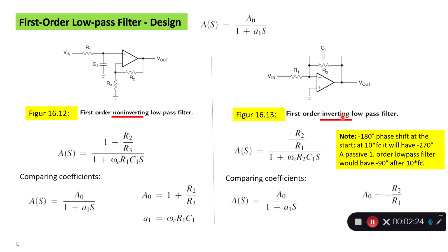If we compare to the inverting low pass filter, we can see that the capacitor is up here in parallel with R2. This is not an uncommon way to design a low pass filter, because it's just to parallel a capacitor C1. But there's a small note. We have this signal inversion, because we have an inverting amplifier where the filter is embedded.